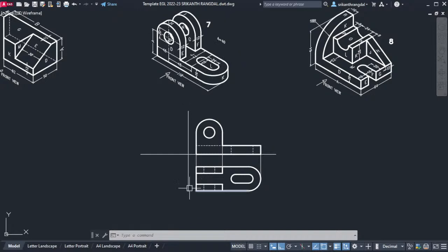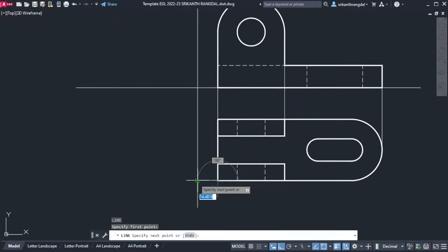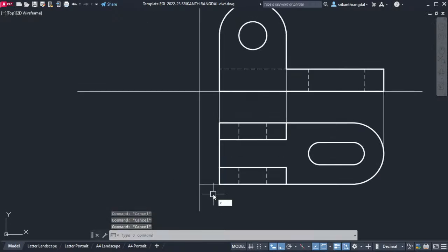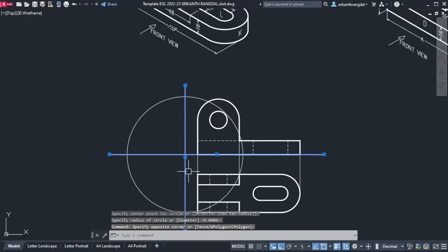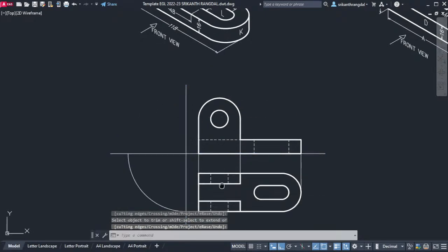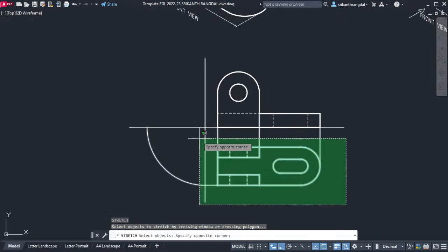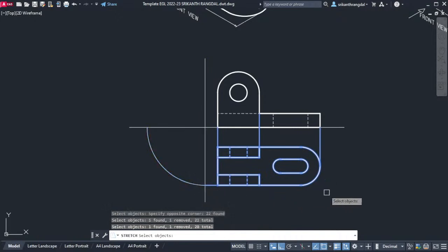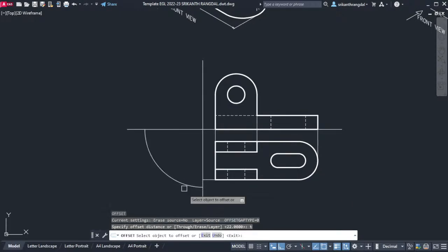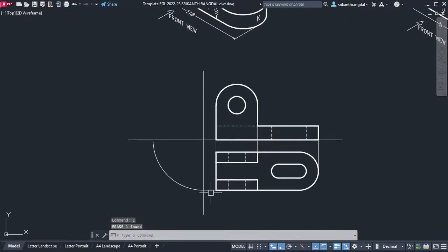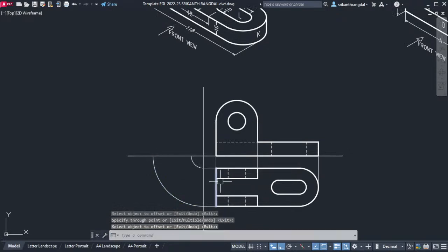So we now have to focus on building the side view. So let's extend this downwards. So take a line from here, then take a circle from here till this point. Then I'll have to trim it, remove these. Again, O enter. Okay, let me just push it a little up. Okay, that should be good enough. So now O enter, T enter. I can use this for getting parallel lines and concentric arcs.